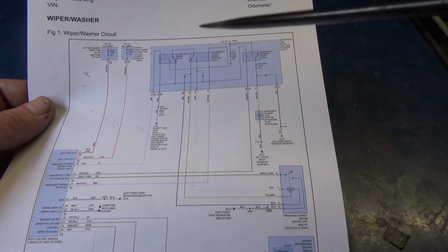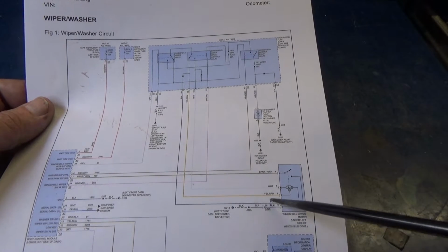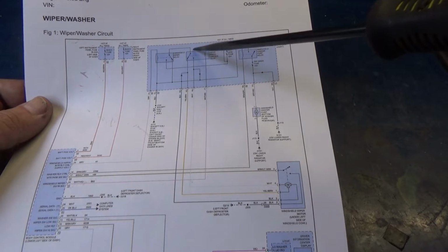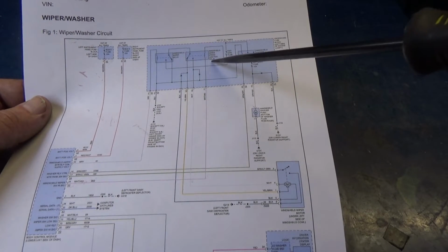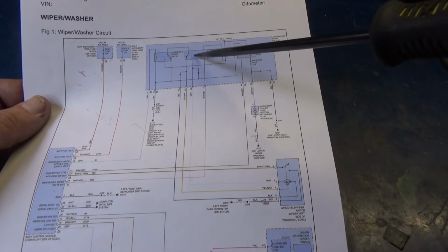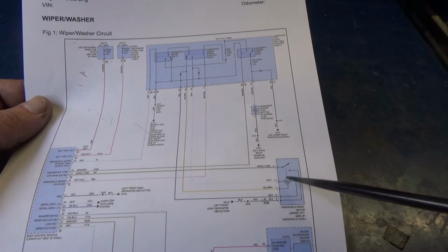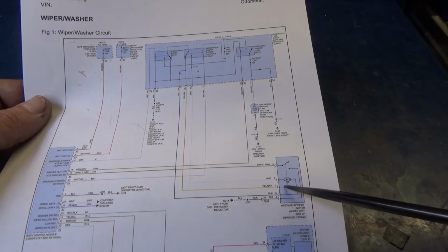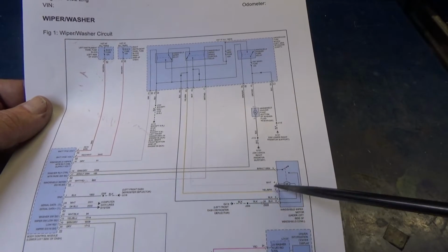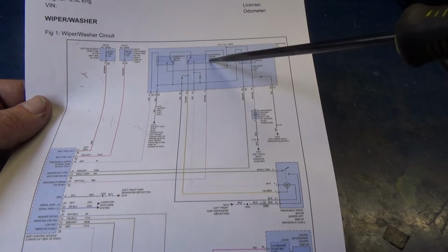So this is my thinking. The motor is probably fine, and the reason I say that is because if this relay was energizing the way it should, and these contacts were going over here on the high-speed set of contacts, that means that the low speed windings of the motor should be losing this yellow 12 volt feed from the relaxed relay.